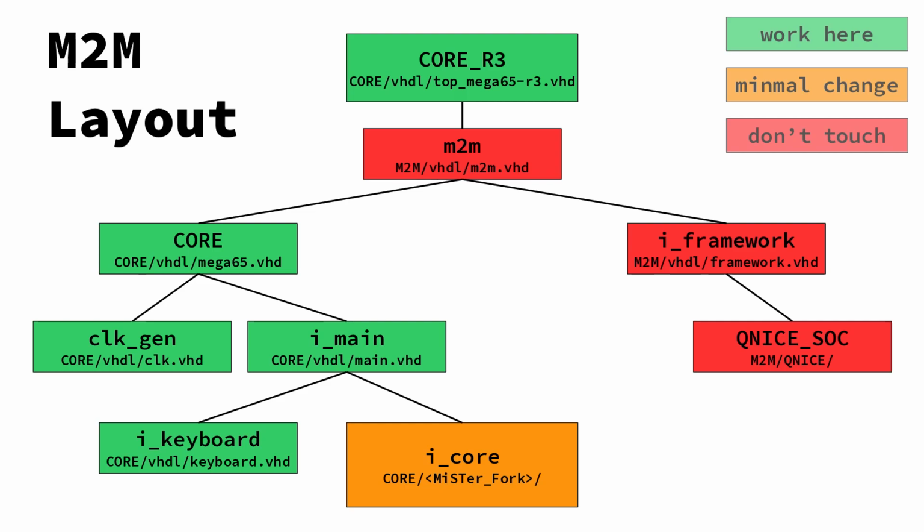The keyboard provides a simple interface to the MEGA65 keyboard, and in it you will be able to implement the mapping logic you need for your core. It runs in the same clock domain as the core, so it can be directly wired to it. For the Democore, the keyboard will simply send a signal that has 1 bit for each key, so essentially an 80-bit signal word. config.vhd controls all the things the user of the core can control and configure.